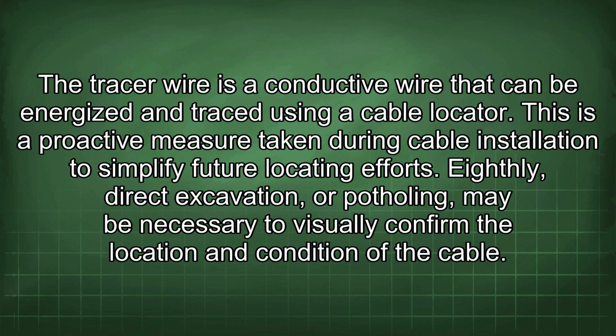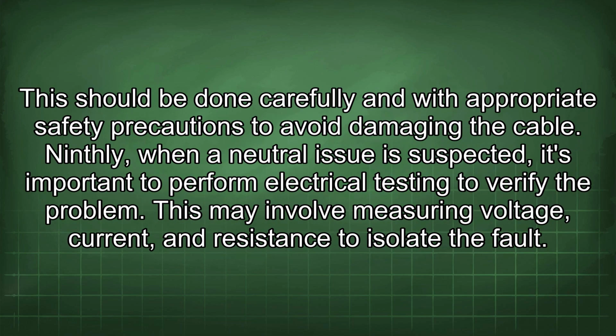Eighthly, direct excavation or potholing may be necessary to visually confirm the location and condition of the cable. This should be done carefully and with appropriate safety precautions to avoid damaging the cable.